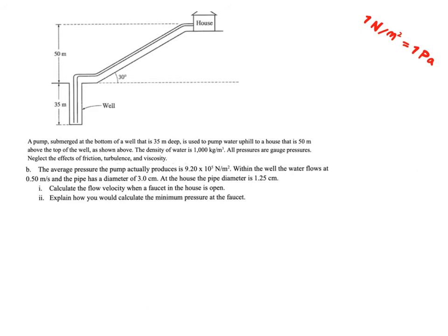So when I'm thinking about this and trying to connect it to concepts and ideas that we've already talked about, that's going to be the following. We know that the pipe diameter is changing from there to there, and of course the speed's going to have to change. Now, we just talked about this in the previous question. We're going to use the continuity equation, A1 times V1 equals A2 times V2. And then we're going to substitute in what we have.